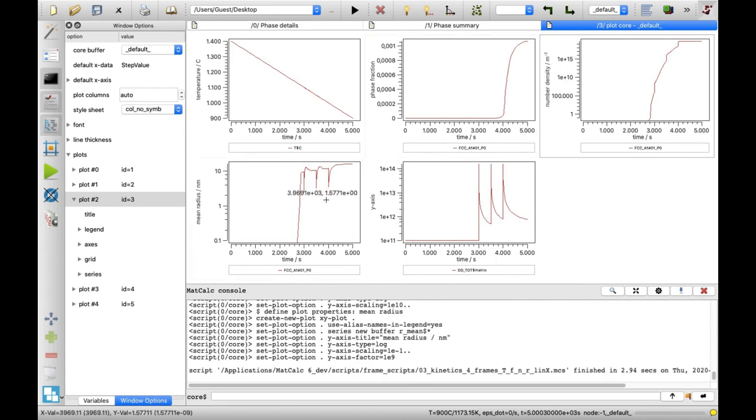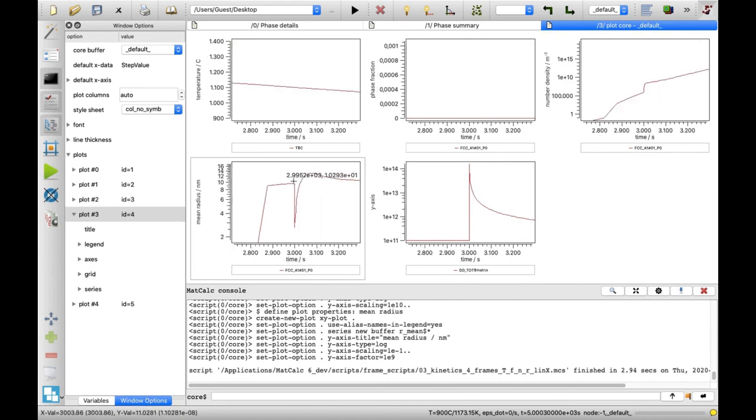Mean radius plot indicates the influence of the deformation on the precipitation growth. First, at each deformation segment, the mean radius decreases, due to the formation of the new portion of small-size nuclei. Shortly after, these precipitates grow very fast, due to the increased diffusivity in the system thanks to the increased dislocation density in the system. This characteristic of number density and mean radius is typical for strain-induced precipitation.